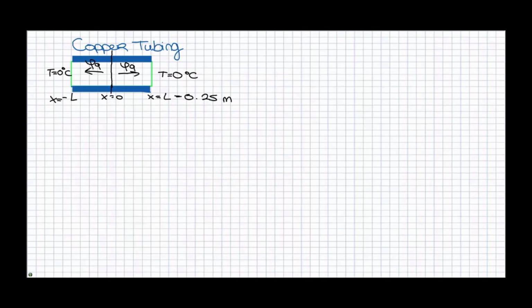The first question was, which balance do you use to be able to calculate the temperature in the middle of the tube? Of course, temperature is all about energy, so you only need the energy balance. And the second question was, which law will you use to describe the flux in the part dx if you set up a balance over a small part dx of the tube? And that is of course Fourier's law, because that has to do with the temperature change.